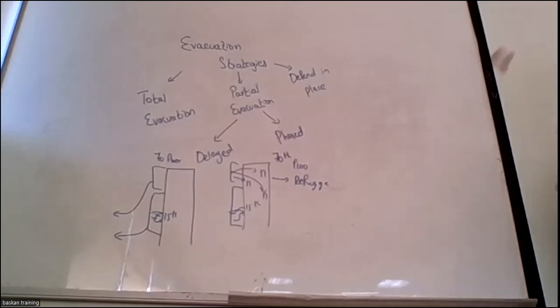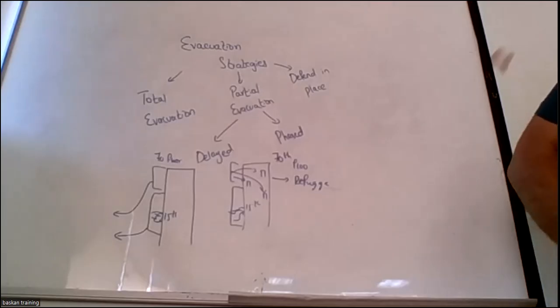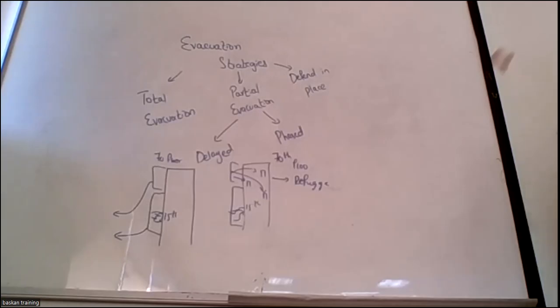There are some occupancies where we don't want the people to be removed from the facility, for example, a person who is in an ICU room, on critical medication, critical machinery. So hospitals, critical operation or critical areas, where ICU rooms are, are well isolated. 3 to 4 hours of fire protection is there, so that they always have one strategy. Their strategy is not evacuation. The hospitals are always designed for defend in place strategy, so they don't have to evacuate.